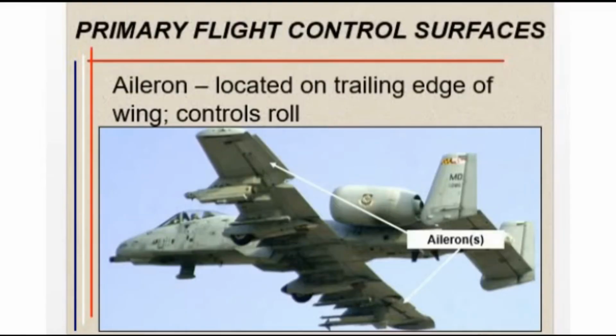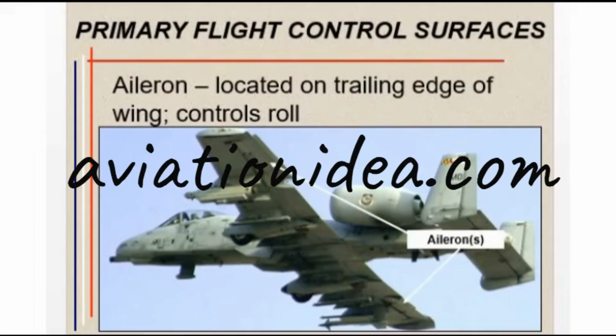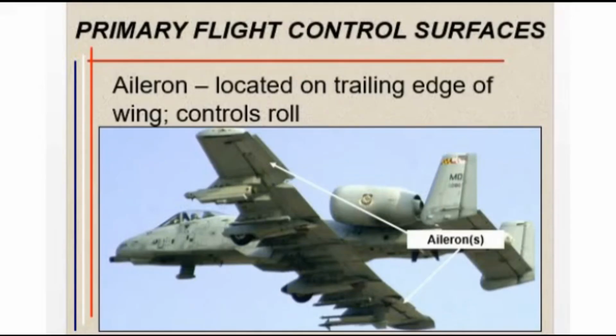Ailerons of an aircraft. An aileron, figure 12, is a movable control surface. They are found in pairs located in or attached to the outer wing's trailing edge on both sides of the aircraft. Their primary purpose is to control the aircraft around the longitudinal axis, or roll, by creating unequal or opposing lifting forces on opposite wings.